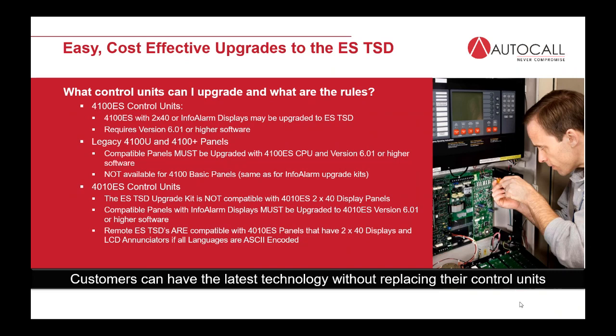From a 4010 perspective, it's not compatible with the standard 4010 2x40 display. Okay, so I'll say again, it's not compatible with our standard 2x40 4010 ES display, but it is compatible with those existing 4010s that are out there that have that InfoAlarm display, and must be upgraded to that Rev 6.01 or higher, just like the 4100 ES.